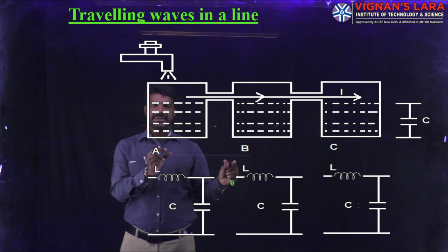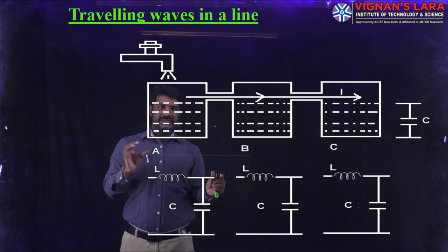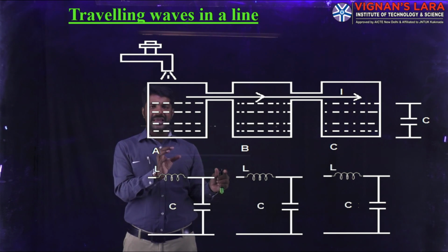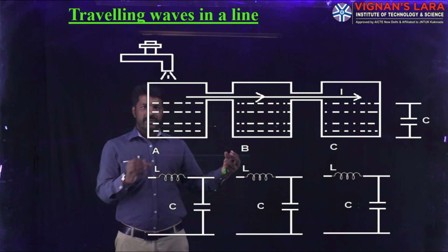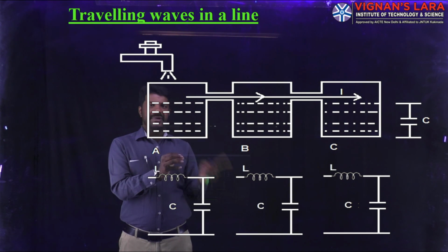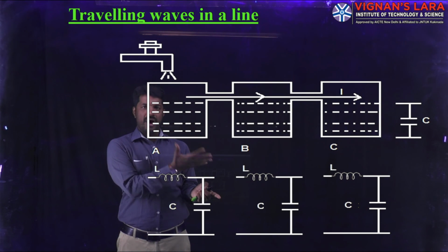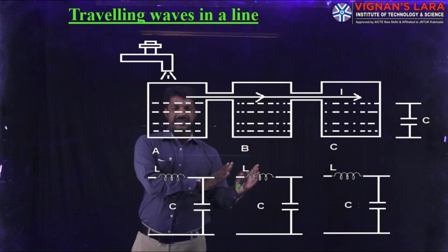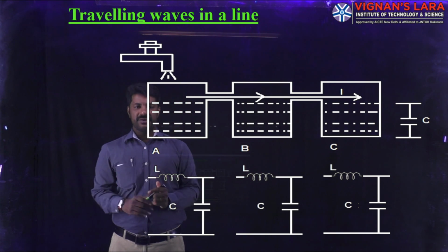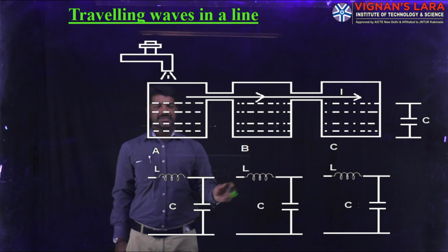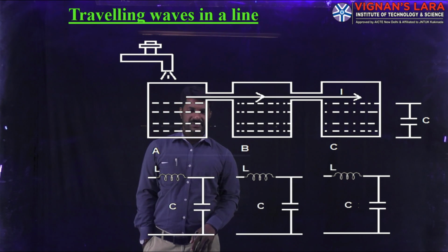In the last class we discussed that characteristic impedance will be in the hundreds, 400 ohms. If such an overhead transmission line is jointed with a cable, the cable has only 40 ohms. So because of the joint there is a disturbance in the ohmic value, and obviously the reflections will start; the voltage and current will start reflecting. This happens on the transmission line whenever the wave moves from the sending end side to the receiving end side.